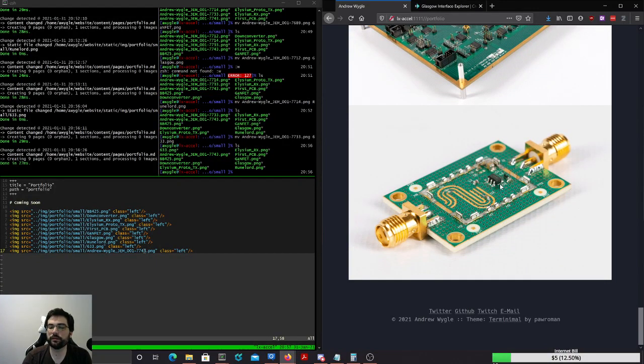So this is just a strap-on board. You can run an SMA through line, and it drops the noise figure significantly just because of how noise cascades work, and it only increased the power consumption. My target was another 25 milliwatts, but I ended up at maybe 10. Honestly, you could run this and the Elysium, and most of the time it would still stay under that 25 milliwatt target, which again, I'm really proud of this design.